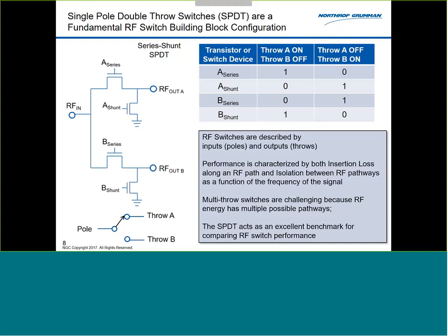When they say it's really low insertion loss, are they talking about the switch, or just the transmission line the switch is running off of? Those kinds of tricks are much harder to do with the single pole double throw switch, and when comparing technologies, I find it much better to make an apples to apples comparison by using a topology like this as your baseline.